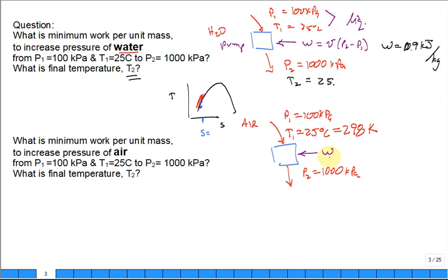We ask ourselves, what does that work? It's the integral of v dP, if you assume it's reversible. We think in our mind we have the image of the pressure-volume diagram going from this low pressure P1 to high pressure P2. Somewhere the process looks like this. It goes like that, right? And it's the area to the left of that curve. If it's reversible, that would be the minimum work.